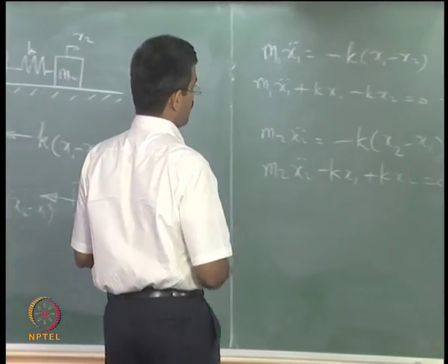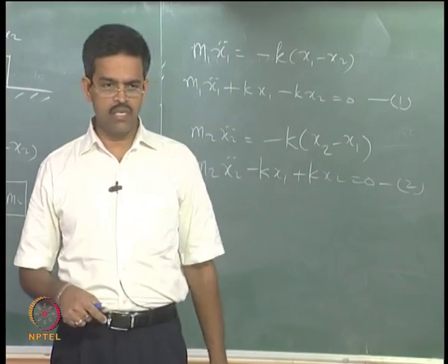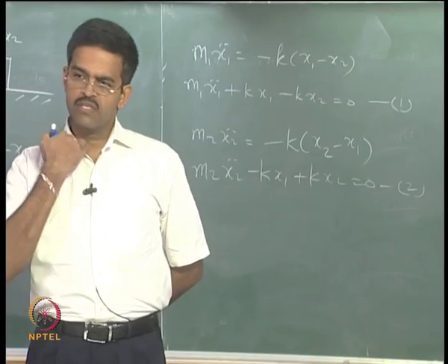Now throughout these examples we understood that when the mass matrix or the mass is lumped at the point where a displacement is measured, the mass matrix becomes diagonal and diagonally dominant, and off diagonal terms are generally 0.